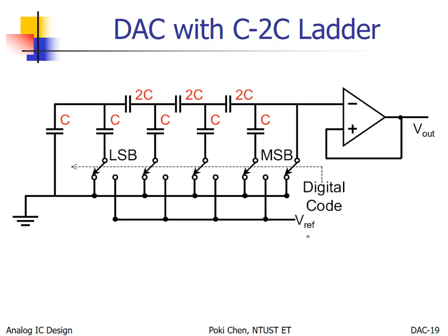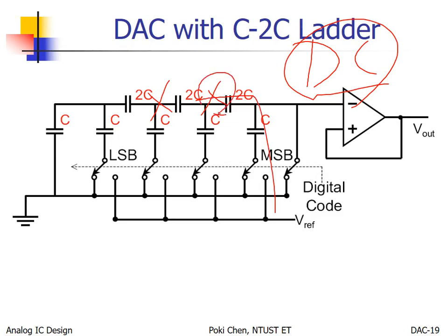If any noise or error accumulates at the points in between, there isn't any DC path for you to dissipate such error or noise. If something goes wrong at those middle nodes, with noise or errors, there is no DC path to discharge them, and you are in big trouble. And this is the reason why we don't. That is only for idea, but in practice, almost nobody adopts such a structure.